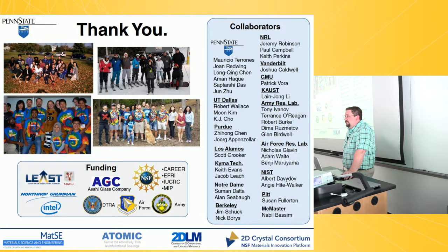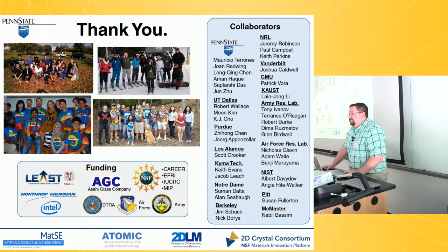Okay, one more. When you're planting your atoms underneath the graphene on the silicon carbide surface, for your growth of the graphene you have the silicon subliming out through those defects to give you the carbon-rich surface for those carbon-carbon bonds. What's the trade-off when you have the silicon coming out, and then the next stage of growth where you actually still want those defects for whatever atoms you're implanting to go in? Have you found any issues with that balance, or any complications with the different rates, keeping those defects and actually having a uniform surface?